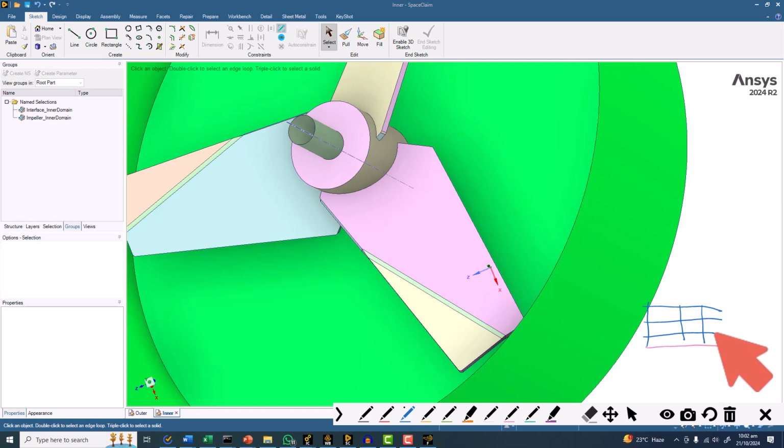So at some locations, what happens is that some of the layers will start to collapse and they may turn into triangular mesh. But in Fluent meshing, we are using the polyhex core, so they will turn into polyhedra.